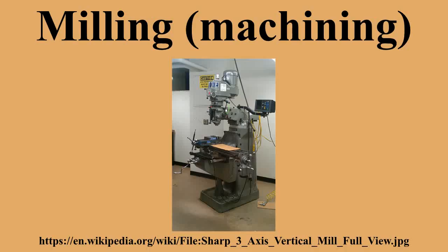These are used to mill grooves and slots. Plain mills are used to shape flat surfaces. Several cutters may be ganged together on the arbor to mill a complex shape of slots and planes. Special cutters can also cut grooves, bevels, radii, or indeed any section desired. These specialty cutters tend to be expensive.